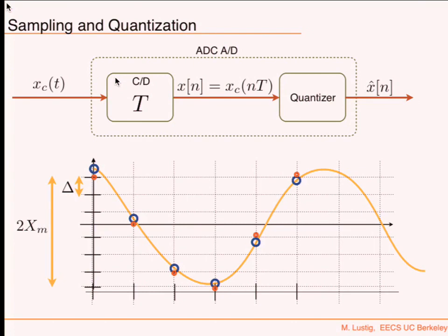I'm going to break that dynamic range into delta intervals, representing the quantization portion of it. Okay? So if 4 bits represent 2 to the power of 4, which is 16, it will break it into 16 portions. So with 4 bits, 16 levels. With 8 bits, 256, and so on and so forth. Okay? So those are the definitions that we're going to be using.